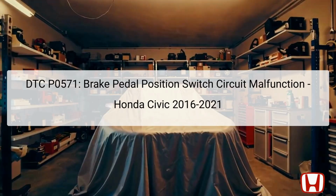The diagnostic trouble code DTC P0571 indicates a malfunction within the brake pedal position switch circuit in the Honda Civic models from 2016 to 2021. The brake pedal position switch plays a critical role in signaling the vehicle's computer system when the brake pedal is pressed or released. It is typically located near the brake pedal assembly within the vehicle's cabin. This switch engages when you press down on the brake pedal, informing the powertrain control module (PCM) to adjust parameters like fuel injection and transmission behavior.